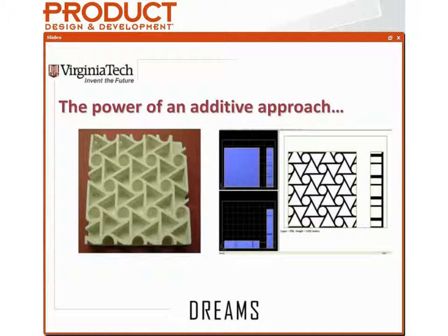What we show here is on the left is an actual 3D printed or manufactured part, and on the right-hand side is an image of a single layer of that part. Now what you see actually are 2 different images on the right. You see one where the part is being printed on its back, and one where it's being printed on the side. Again, in additive manufacturing, orientation doesn't matter. The fixturing is not a problem, so we can actually print in any orientation. So what you see are actually 2 layer representations of that same part.